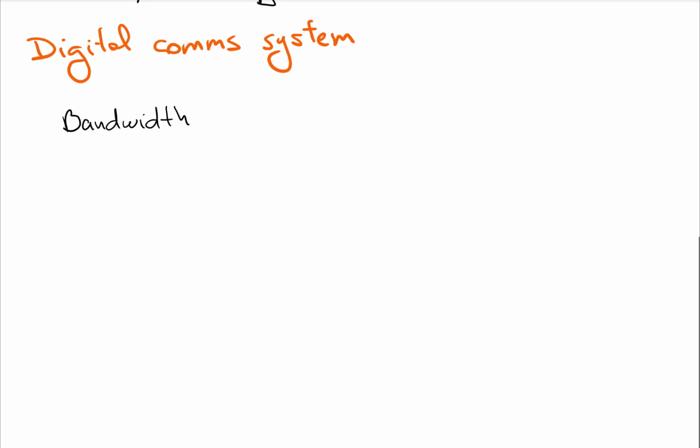Okay, so now, an important objective in the design of a communication system is often to minimize equipment cost, complexity, and power consumption, whilst also minimizing the bandwidth occupied by the signal or the transmission line. Bandwidth is the measure of how rapidly the information-bearing part of a signal can change, and is therefore an important parameter for communication system design.